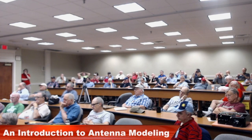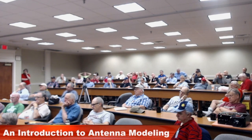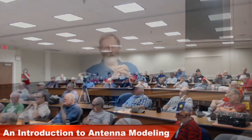So the best antennas on 160, given a height restriction of something moderate like 80 feet, are going to be vertical antennas. Now, vertical antennas typically want ground radials to work well unless you can make them actually a balanced antenna. So a vertical dipole is a pretty decent vertical antenna. It doesn't need any radials. So I was working on a vertical dipole, and I came up with a scheme where I would run a wire from the big tower to the little tower, and then another wire from the little tower to the ground. So it was sort of like a sideways inverted V.